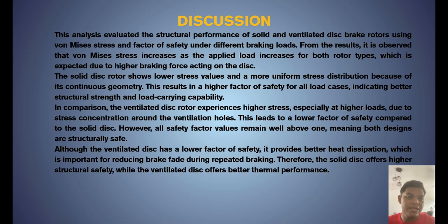Although the ventilated disc has a lower factor of safety, it provides better heat dissipation, which is important for reducing brake fade during repeated braking. Therefore, the solid disc offers higher structural safety, while the ventilated disc offers better thermal performance.